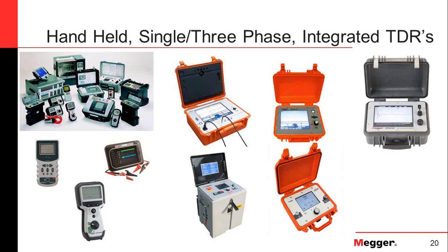We have partial discharge testing, which combines a creation of partial discharge with a TDR technique. So there's TDR techniques used in diagnostics of cable, but just to hook a low voltage TDR up, it's not capable of seeing water trees or anything like that on its own.